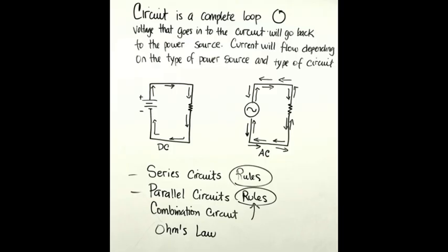Alright, my next step would be R total equals 1 divided by the sum of these three. So I have to add them up. At this point, I have to add these three values. So it's going to be 0.25 plus 0.05 plus 0.2. That would give me 0.5. So R total equals 1 divided by, let me go slowly, guys, okay?